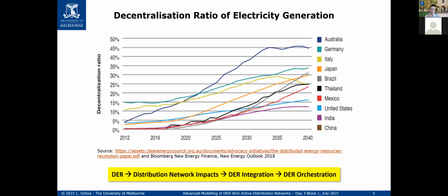So that's why we're moving, first to understand those impacts, and they are already happening in many countries, and then to integrate. So we're moving to integrate distributed energy resources, which is essentially, okay, how can we fix things as soon as possible? That's where standards come in: volt-watt and volt-var functions for photovoltaic systems, level 1 and level 2 charging, which is essentially limiting the amount of power that you can withdraw at a charging point with your electric vehicle. And that's all good, but that's not enough. That's not necessarily a clever system that can really do things actively.